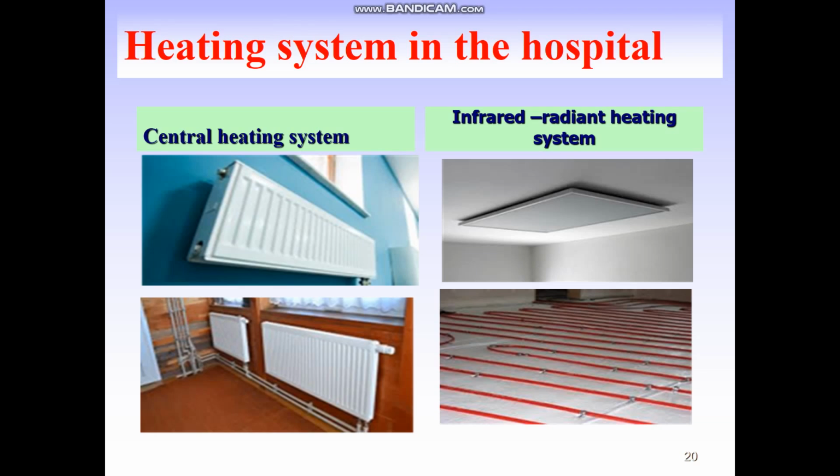In hospitals central heating is usually provided. The water temperature in the heating device is not over 85 degrees. More hygienic requirements are met by the radiant system, panel heating. Radiant heating is recommended for aseptic premises: operating rooms, maternity and neonatal wards, burns, and infection wards.